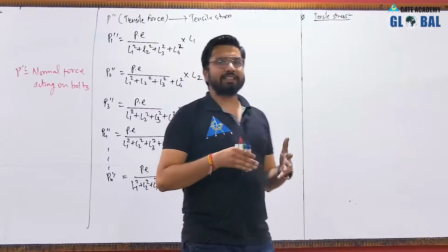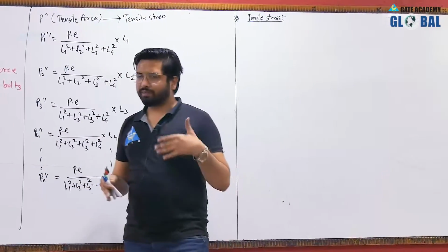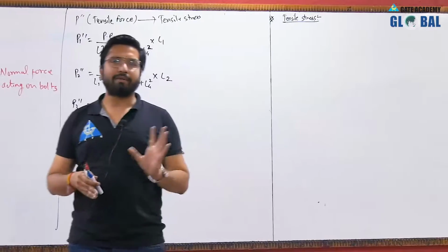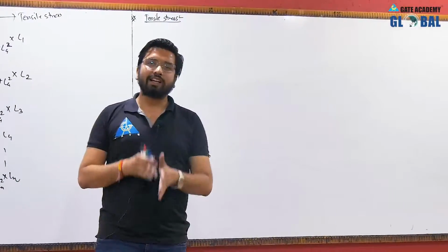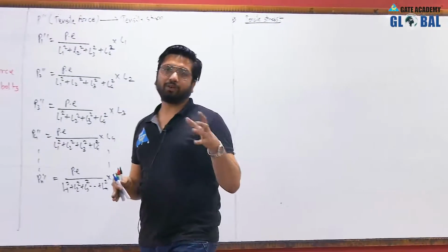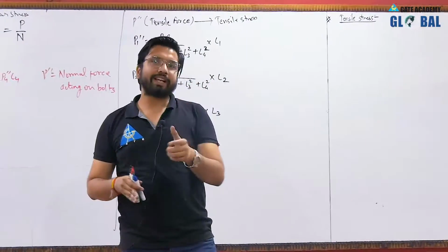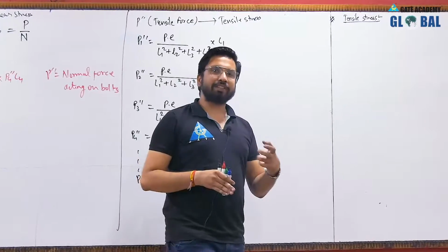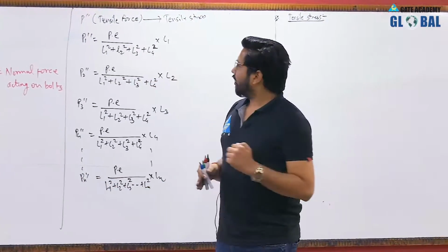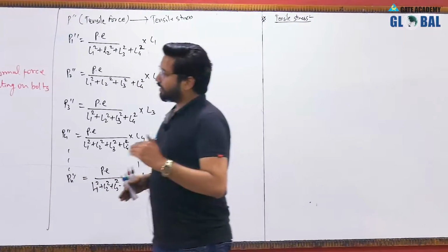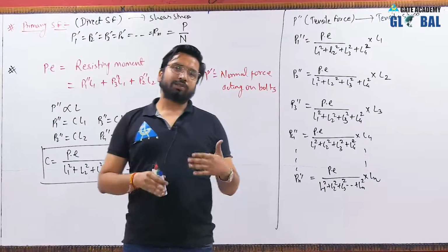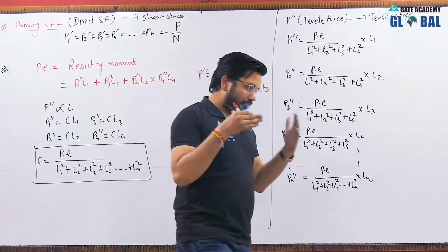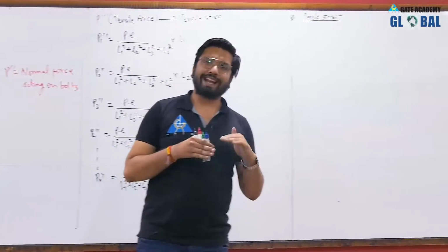But if the data is not given like that, in that case we may consider the shank diameter also. But for the majority of cases where there is a tensile loading in the bolt, we will be considering the core diameter, because in tension the core area will be the critical area at which the maximum stress will be produced, okay. Now here, as the shear stress is being analyzed in the shank portion, it becomes mandatory to solve the problem for the shank area only, okay.